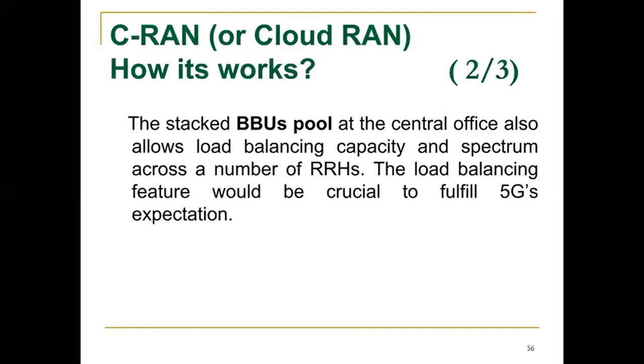So the stack of the BBU pool at the central office also allows load balancing of spectrum across a number of RF radio resource units. The load balancing feature is crucial for fulfilling 5G expectations. Remember, 5G uses a very costly spectrum chunk, that is the gigahertz spectrum, and the spectrum is very costly. And if the companies effectively use these radio resources, they can save a lot of money. And the way to save the money is to centralize the use of baseband units.